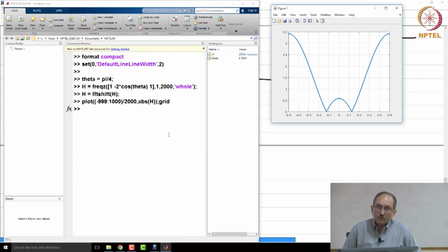Yeah, that's okay. As far as we are concerned, we are mainly interested in notching out. The fact that the gain is much more than 1 brings out one more case against the simple notch filter, in that it is far from ideal. So the gain being much greater than 1 is a case against it, for its departure from ideality. Of course, at plus 0.125 and minus 0.125, the gain is exactly 0.